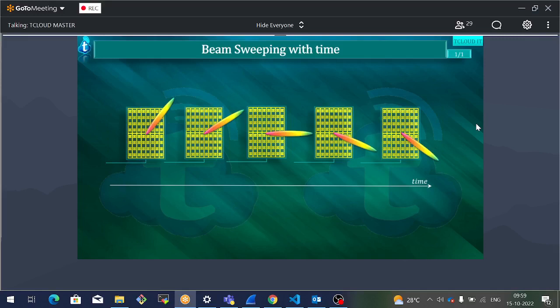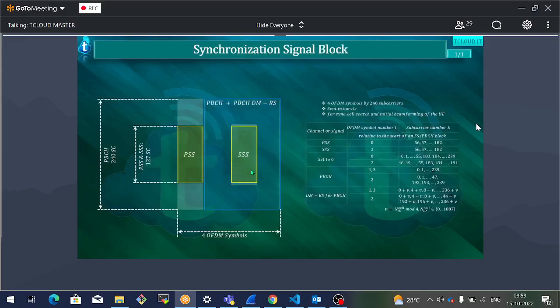Okay. Now we have introduced this common channel called SSB, synchronization signal block. So what is this, and why is mobile equipment required to detect this synchronization signal block? I already gave you the problem statement. Mobile suddenly came up sometime in the cell, in the frame structure. It needs to detect where it is. So one way it can identify where it is, is with the help of this synchronization signal block. How can this help you?